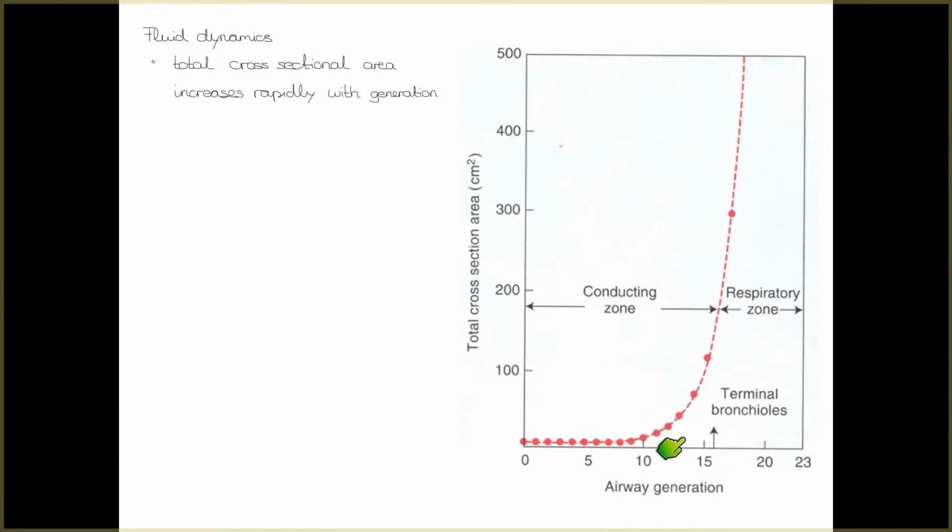And again, when we think about the velocity, as somebody has said before, the velocity goes down inversely to this, because when we look at the continuity equation for incompressible flows, or we can just say it's approximately incompressible because the density doesn't change. It's the same density essentially in the lung. And the increasing cross-sectional area means decreasing airway speed.